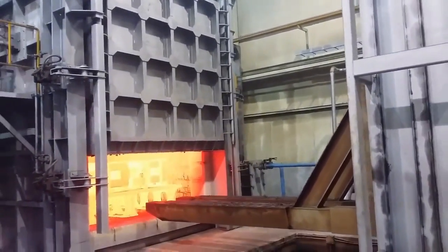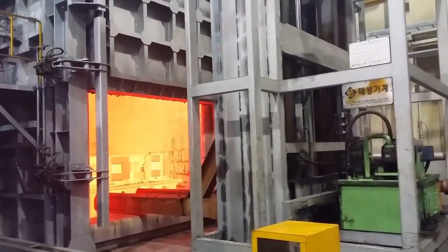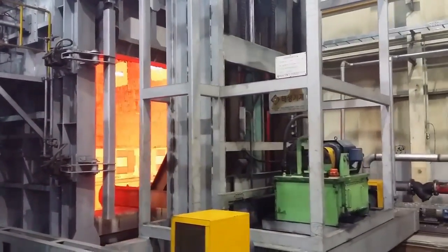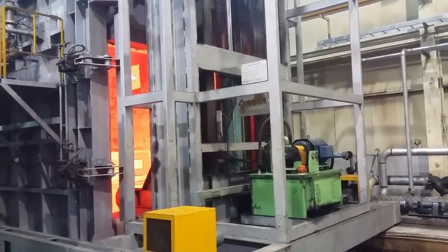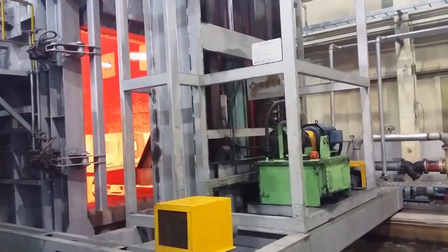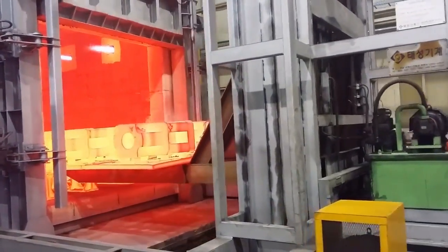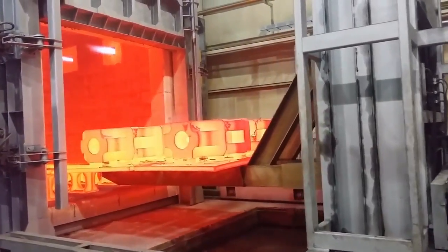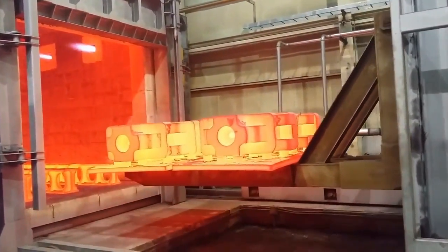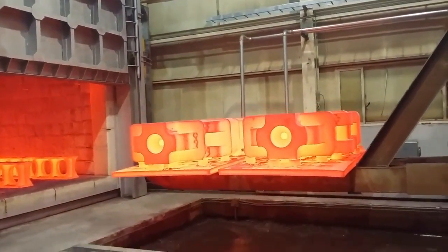Annealing of steel involves heating it to a specific temperature and allowing it to cool at a specified rate. Doing so removes impurities in the grain, increasing the metal's ductility and reducing its hardness. This relieves the internal stresses from the steel and softens the material, which makes it suitable for a wide variety of applications, such as the utensils we use in our everyday life.